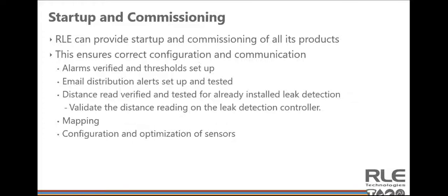We want to do a few things here. Test the system and load it up to make sure it's working as it has been designed and built, and to make sure that anyone who has any interest in maps or the communication of that device to another building management system, if so equipped, is functioning properly. We do inspect cable. We make sure anything that happens during construction, such as, hey, the air handler guys came in and bumped a cable or cut a cable, we make sure all that stuff is taken care of and get you up and running quickly.